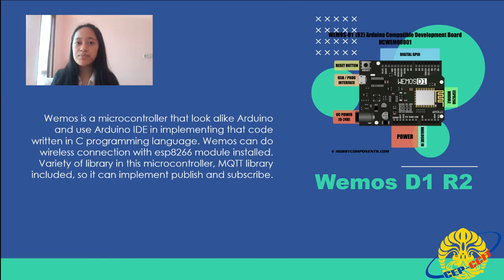Next, I'm going to explain the next tools that we use in the paper. The tool is Wemos D1R2. Wemos is a microcontroller that looks like Arduino and uses the Arduino IDE, with code written in the C programming language. Wemos can do wireless connection with the ESP8266 module installed. There are a variety of libraries for this microcontroller, MQTT library included, so it can implement publish and subscribe.